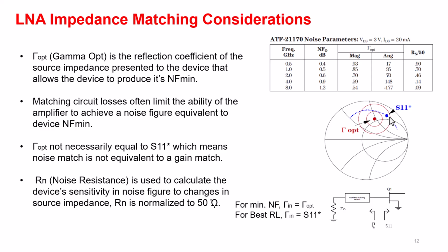That means when you are looking to match the input side of your amplifier, trying to achieve a best possible S11, that may not be possible. So input matching is always a compromise or a balance between the return loss and the noise performance, and that's where the most critical designer's acumen is tested, how to find the best compromising point where you can get best of both of these worlds.